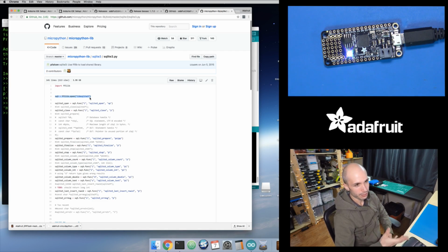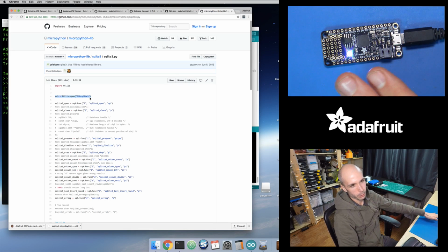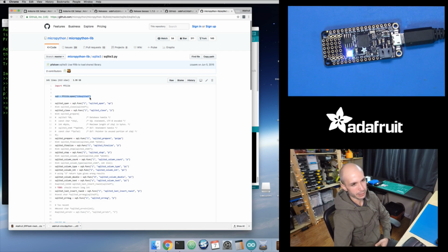And in those systems, it could use SQLite, because SQLite is just a dynamically linked library, so we could load that library up. Whereas on your ARM Cortex chip, you have no operating system, so you have no concept of shared libraries. If you try to take a Unix dynamic library, there's no way to load that code. There's no kernel to interpret it. So long story short, it doesn't look like SQLite will work on your microcontroller with MicroPython right now.